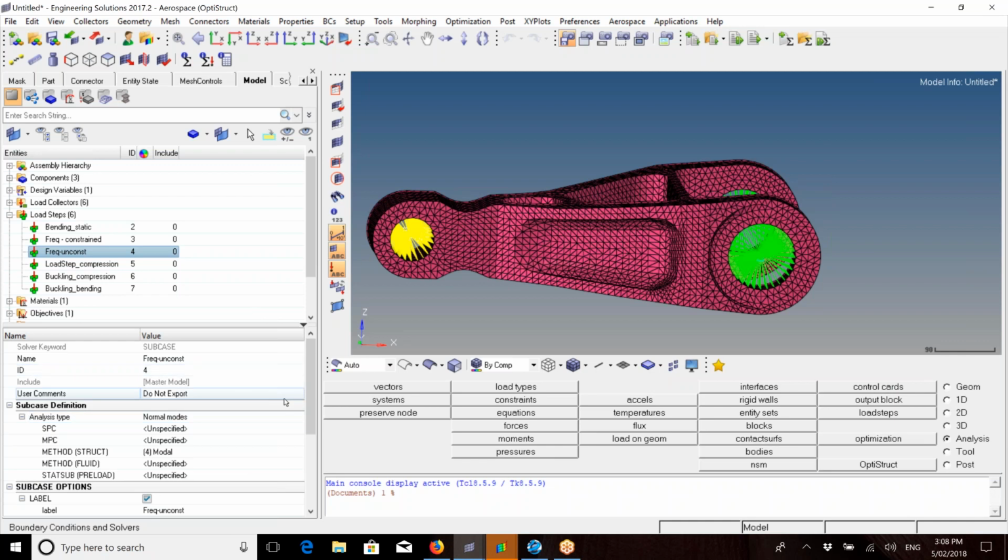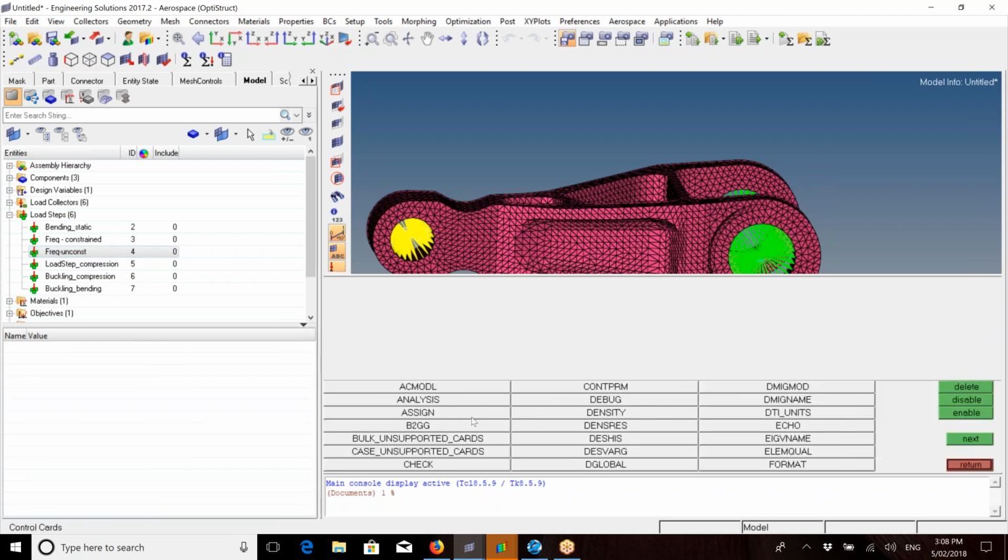So this just gives you your standard 2D stress and strain, but I'll show you where all control cards are as well for any output. Control cards in analysis, and then you can go through all these, and again you can find information on all these different cards in this help section. So it really is a good handy spot to go.